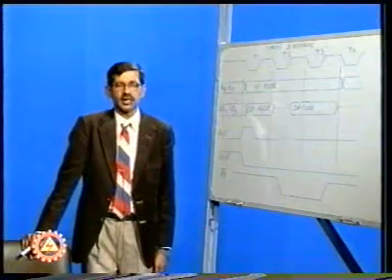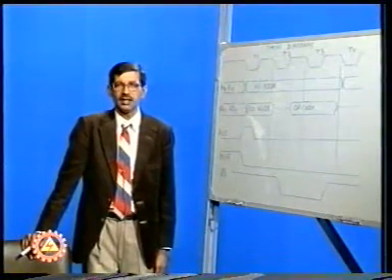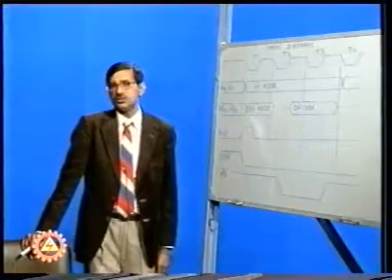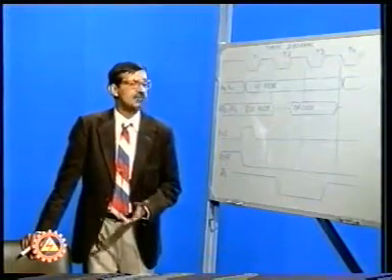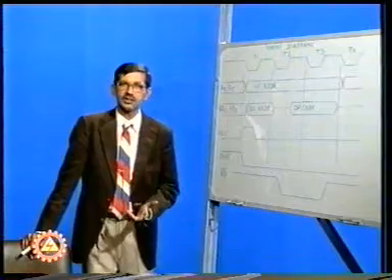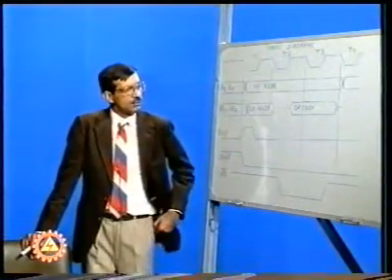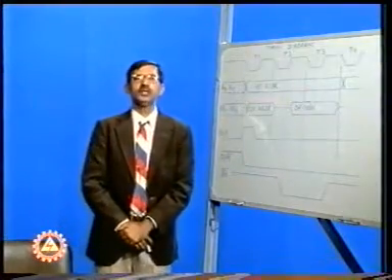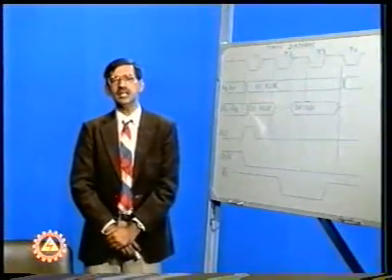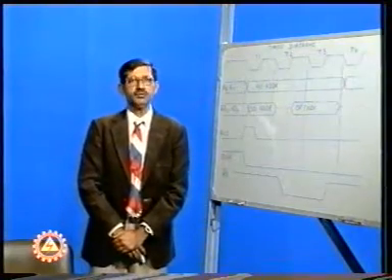Each instruction cycle has a number of machine cycles. Each machine cycle is defined as the time required for having access to the memory. The number of T states in a machine cycle could be from 3 to 6, and each instruction cycle may consist of up to 5 machine cycles.